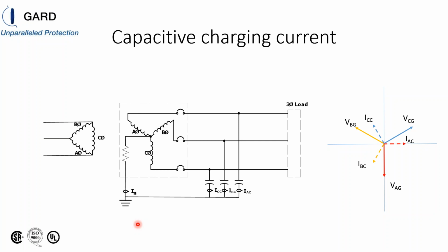So you have one potential in your conductor, an insulating medium around that conductor, and then a ground plane usually on the outside. It could be laying in a cable tray, it could be laying in a conduit. So you have two potentials isolated by an insulation medium, and that's called a capacitor. So we have distributed capacitance.